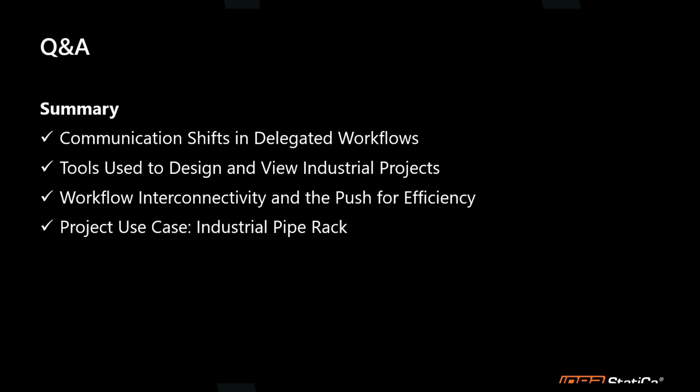Yeah, there are questions about the position of the force, if it's on bolts or nodes. This is one of the boundary conditions of IDEA StatiCa. In a recent webinar that I did, I have this rule of thumb: if the member has only shear force, then this is when it's important. So if it only has this shear force, then you need to specify the software where you want that shear